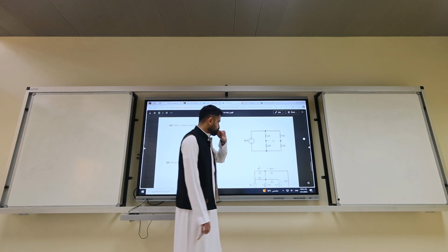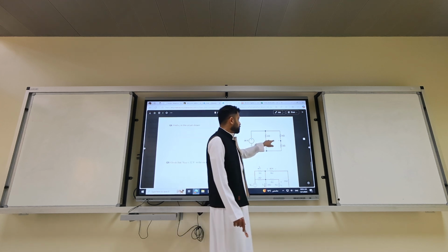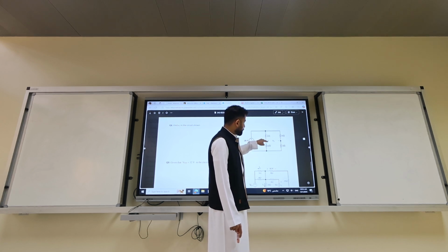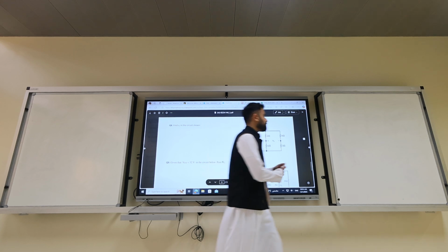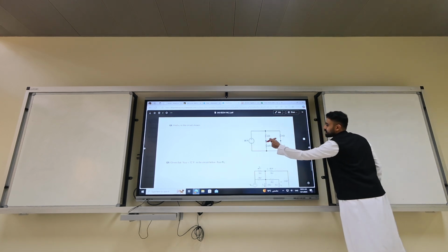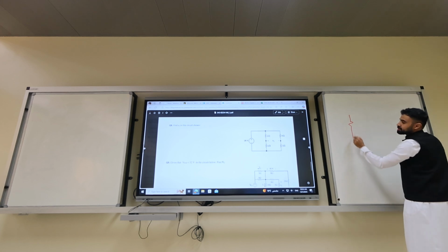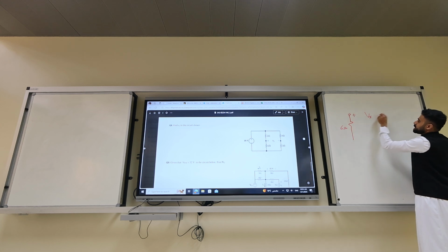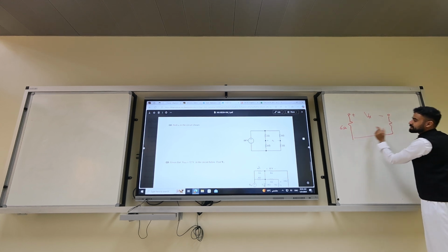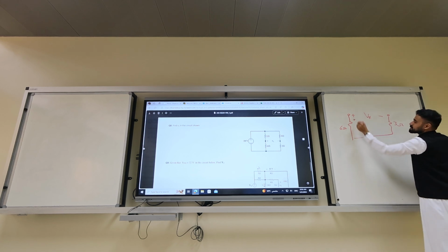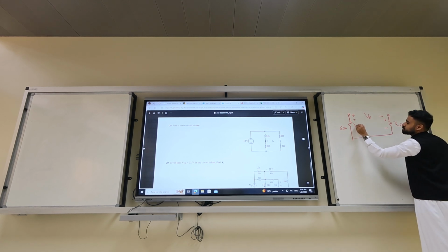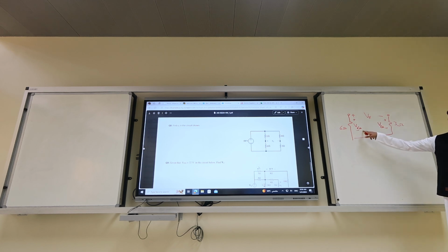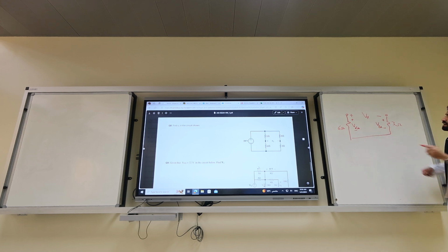So for this question, Vx, you do a KVL around this open loop, okay? If you put plus or minus, let's put, this is 6 ohm. Think of Vx as like this. This is 3 ohm. Then you put plus minus, and then you can write V6 ohm, V3 ohm, meaning subscript of 6 ohm. And then we do a KVL.